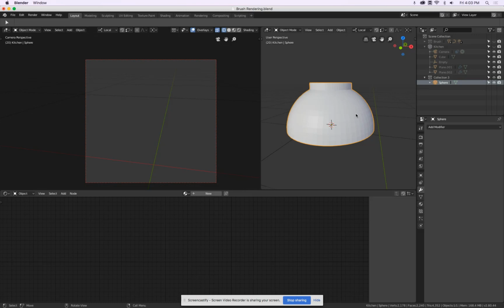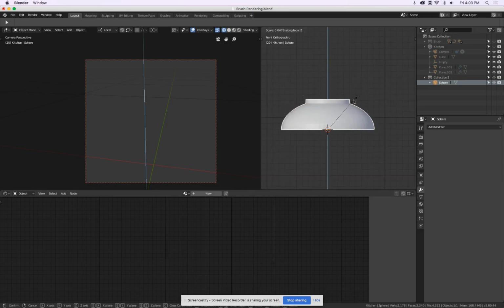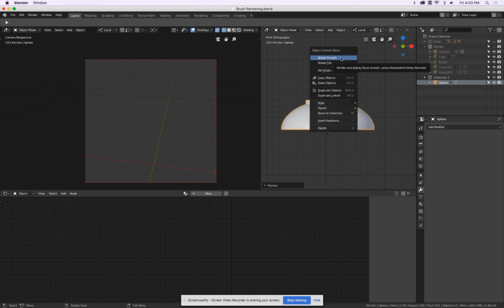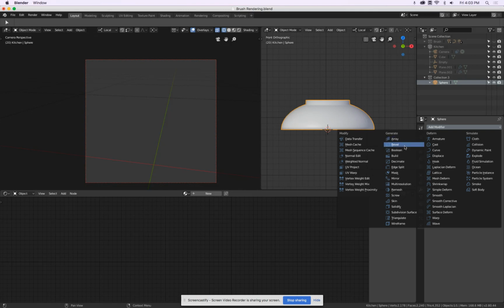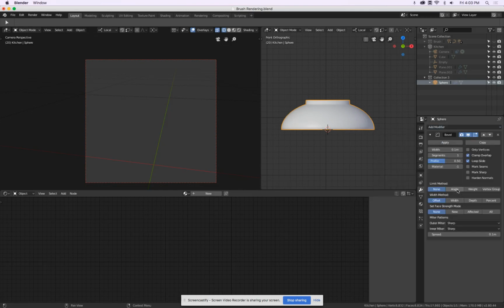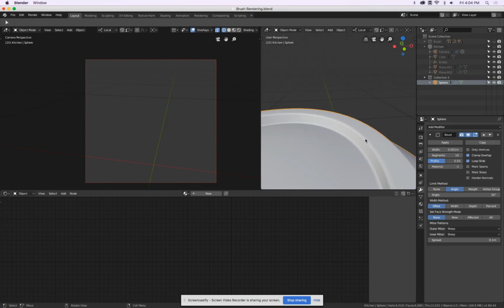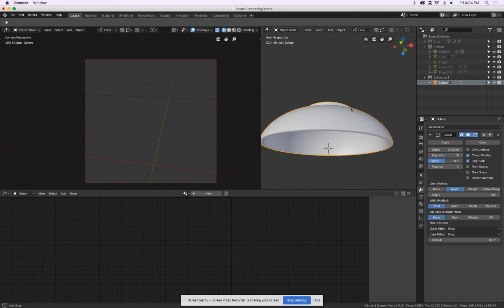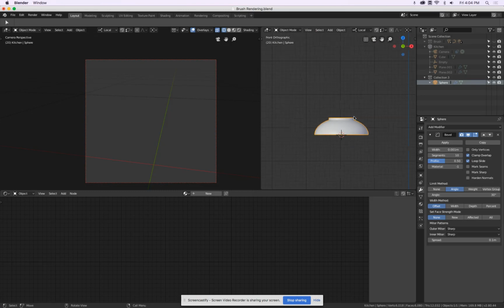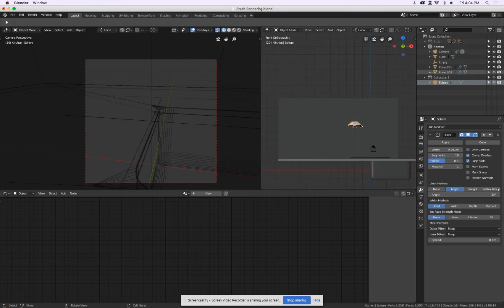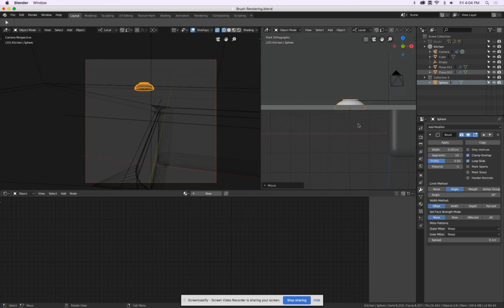Here we have a small bowl now. See, not too complicated. Maybe we can flatten this a little bit. Then shade smooth, modify bevel, only sharp edges by 1 millimeter and 10 steps. See, that rounds these parts, keeps the rest untouched. Very nice. Let's show the kitchen. There it is. Now we bring this one down.